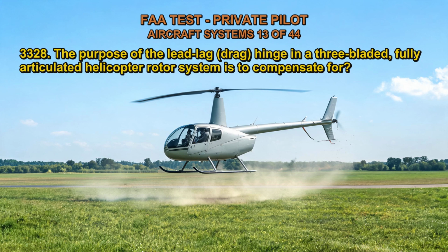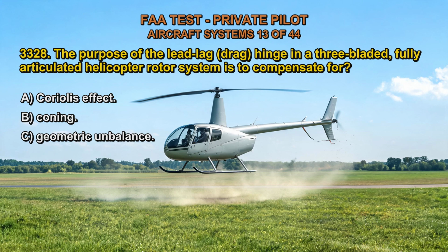Q3328. The purpose of the lead lag, drag, hinge in a three-bladed, fully articulated helicopter rotor system is to compensate for A. Coriolis effect, B. Coning, C. Geometric unbalance. The correct answer is A.